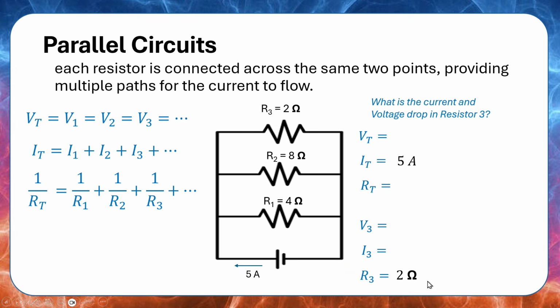Okay, put the R3, which is 2 ohms, and this time let's find out some other values that will be solved using the data that we have in our diagram. We can find the total R, right? But not like the series. The series, you just add them up and you can get right away the total R. But here in parallel, you need to do the sum of all the reciprocals.